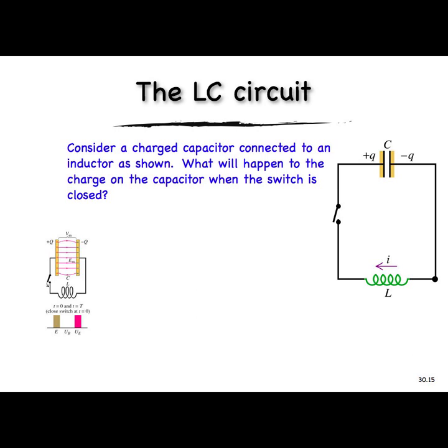And then when I break this, I'm very rapidly changing that current. So there's a very large di/dt. So there's a very large EMF that builds up due to the inductance of these three times that di/dt. So the EMF that builds up can be much larger than the voltage that I was initially driving the circuit with. Now, it doesn't last very long.